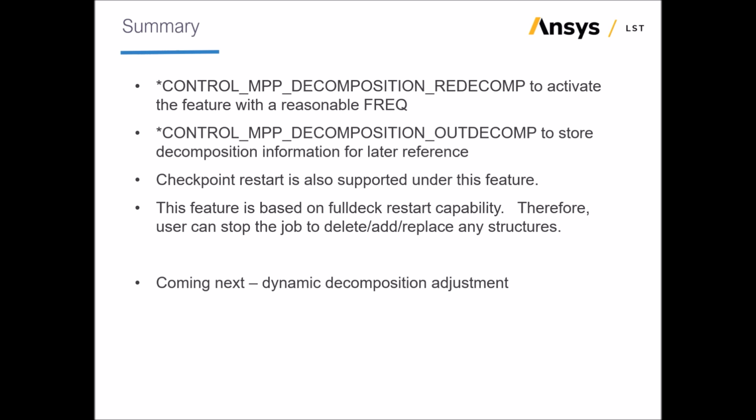This feature uses the same restart file as the so-called full deck restart. So there is some flexibility about not just doing the re-decomposition, but at the same time modifying the model in some way, or rerunning certain parts of the analysis at a later date. There is a further development underway at LST, in which the analysis dynamically shuffles elements from one domain to another during the solution, without needing to stop, write and read large files. This dynamic re-decomposition is not yet ready to use, but watch this space.